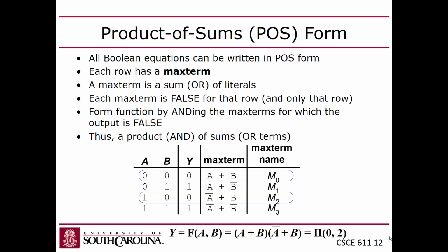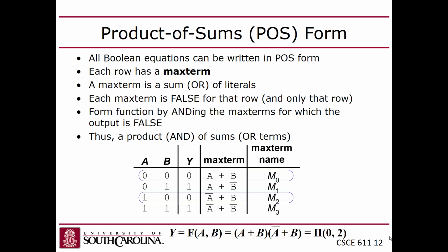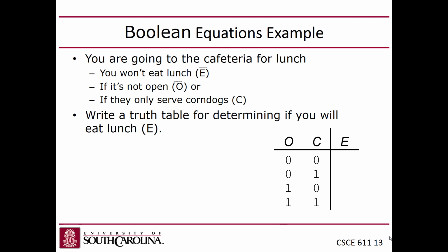And the problem is that generally speaking, you're not going to have that. You're going to be limited in your gate library. Most of the time you can have 2 input gates and 3 input gates. Sometimes you can have 4 input gates, but never any more than that. So we'll talk about how you deal with that in a minute here. This is just an example of how you can build.